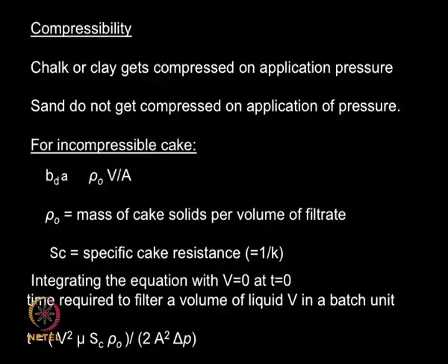So in such situations, by increasing the pressure we will be able to increase the rate of filtration. So for incompressible solids the rate of filtration can be increased by increasing pressure, whereas if it is a compressible solid like clay or chalk, by increasing the pressure you are in trouble, you will be reducing the flow because the material gets compacted.